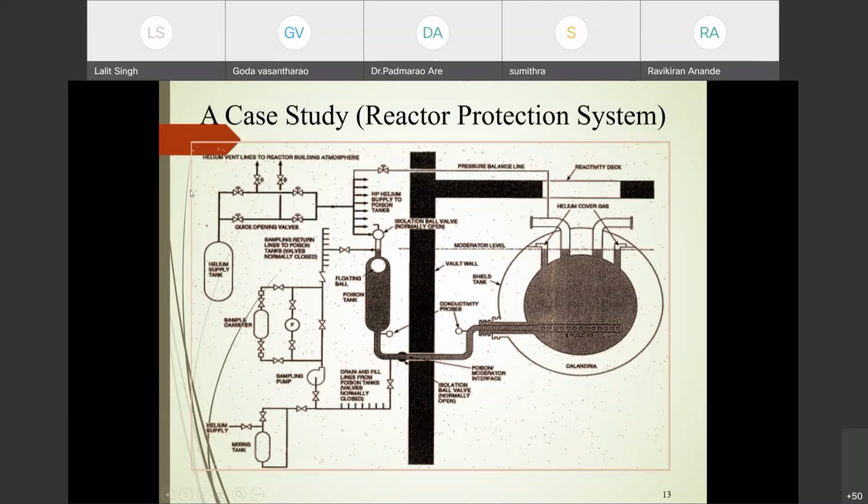To tackle this scenario, it is advisable to put one more valve in parallel, so that if one fails to open, at least the other can open, and the helium pressure can be passed through the other valve, and I could serve my purpose to shut down my reactor. But then why are more valves required?